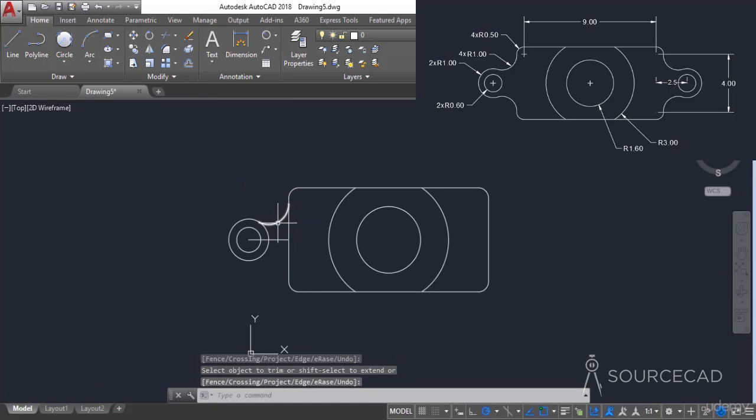Now we can make a mirror image. So I'll go to mirror, select this portion, press enter, click on this midpoint and click on the center, press enter again. So now we don't need this part. Also, we don't need this portion. So I'll go to trim tool, press enter and remove this portion. Now we need to make a mirror image of this on this side.